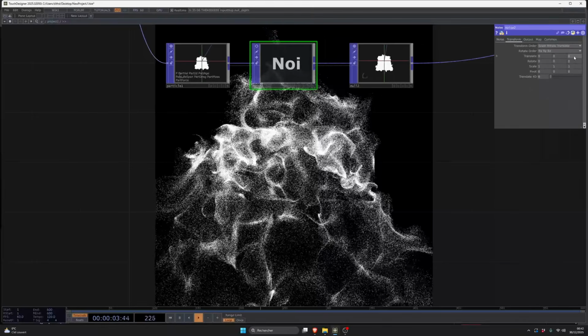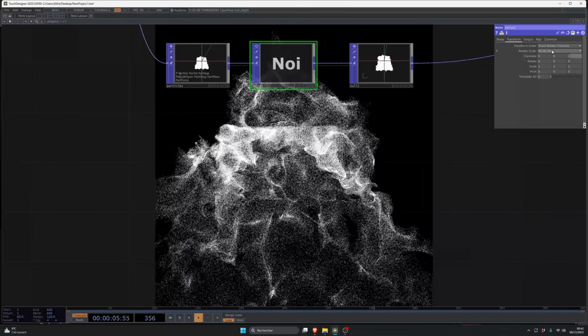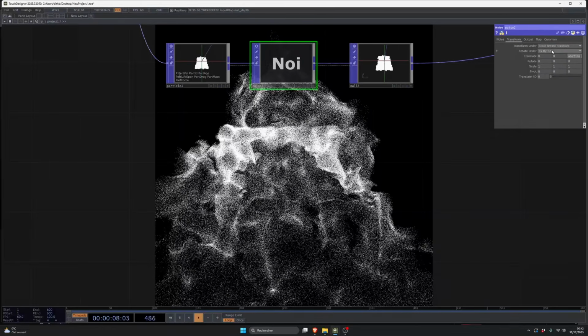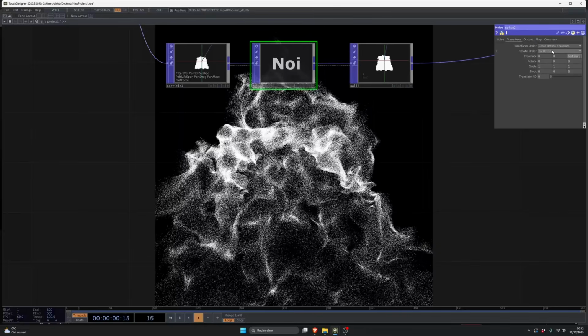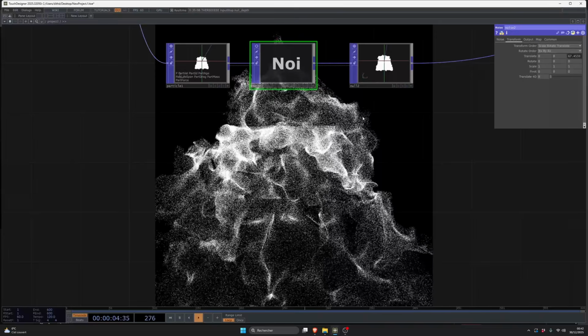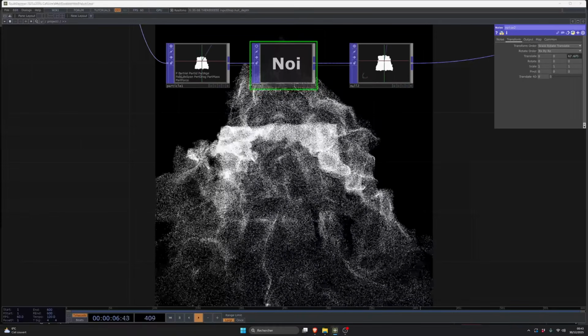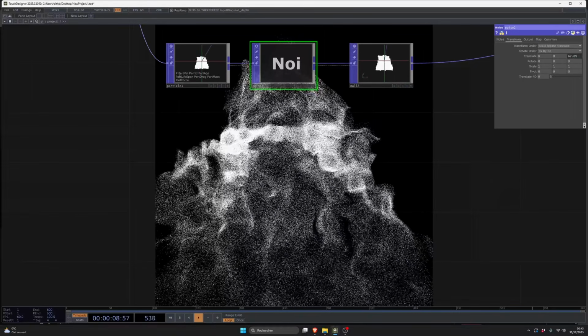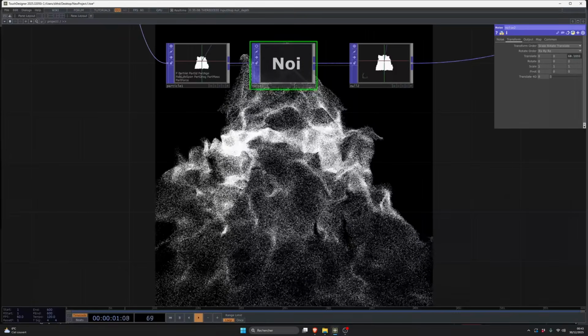And then in the transform, we are going to slowly shift the noise over time, so it's not creating always the same path. So uptime.seconds, maybe multiplied by 0.1. Let's see. And yeah, seems quite good. We can see it's slowly shifting, but not too much neither.